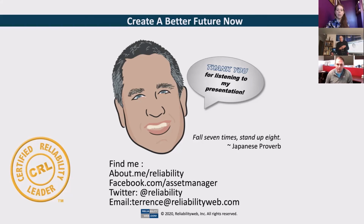If you're looking for performance indicators, I would look for removing maintenance. We're looking to remove corrective maintenance especially, but even proactive maintenance. We want you to do less proactive maintenance. First quartile companies spend half the hours on proactive maintenance and half the hours on corrective maintenance as fourth quartile. Fourth quartile is doing a lot more proactive maintenance, spending twice as many hours doing it, but they have twice as many correctives as well. So you have to focus on those technical failure modes and drive those out with that bad actors report.